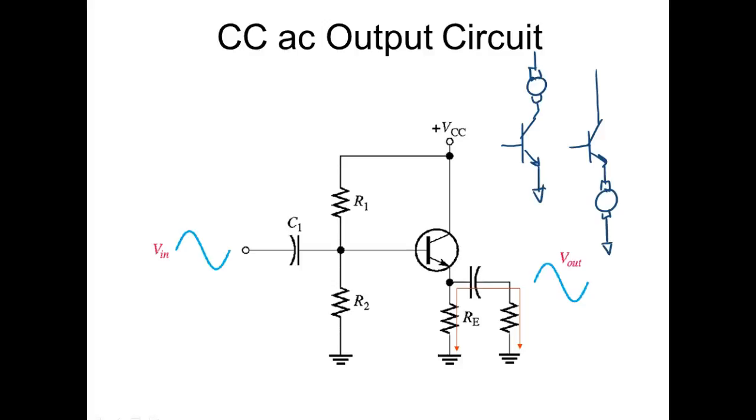Well, if I was going to run it, let's say from a digital supply, and my input was 5 volts, and I wanted to run a 12 volt motor, then I would use this one right here, because I can get a voltage gain out of a common emitter, right? So if the voltage I was going to run the motor on was higher than the voltage I'm trying to control it with, then we'd use a common emitter.